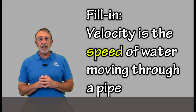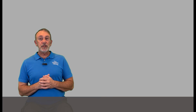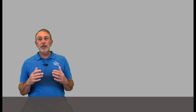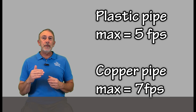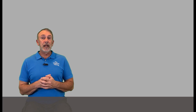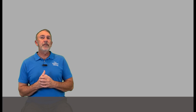And so velocity is the speed that water is moving through your pipe. And that's measured in feet per second, or FPS as we usually abbreviate it. What we're trying to do is keep our velocity below a certain level, right? In PVC, we want to keep it at 5 feet per second or less. And in copper tubing, it's 7 feet per second or less. And I think if you're looking at polyethylene and PEX and so forth, that's also 5 feet per second.